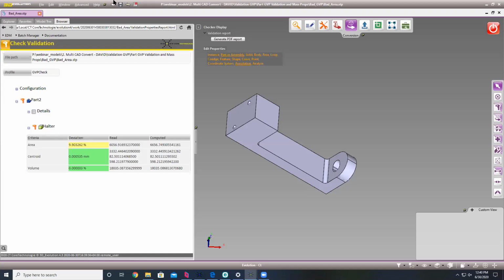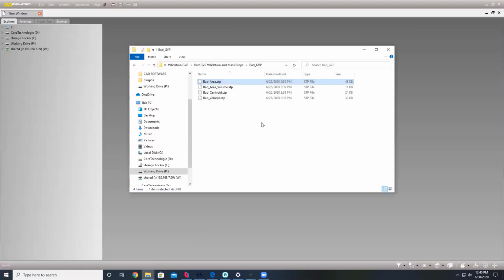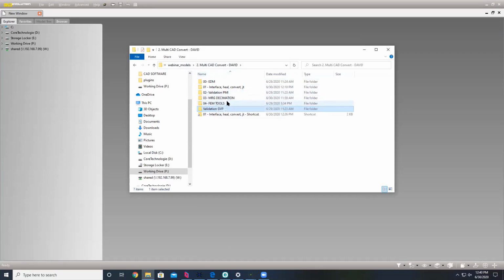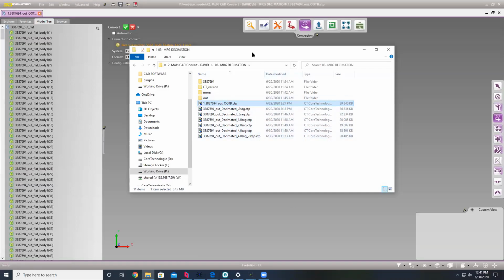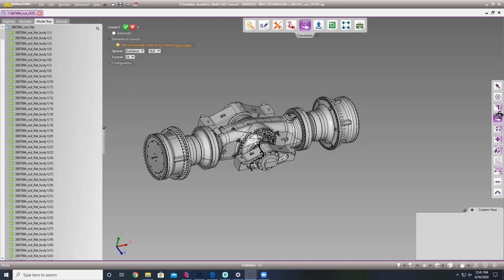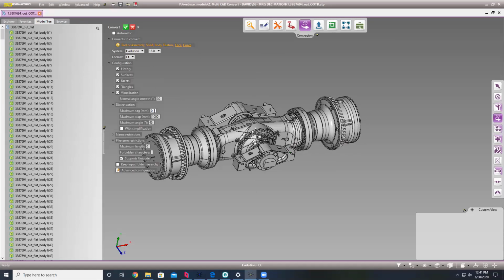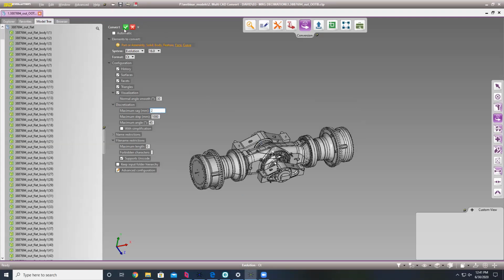And at this time, I have run out of time. But Michael, I know I'm out of time. Can you just take this file and save it with decimation, or show them the results of it? One of the things that happens in the industry is sometimes you're just visualizing a file, and we use MGR decimation to reduce the file size, because some of these files get really large. He's just going to hit file and save, but he's going to decimate it. And when I talk about configuration of decimation, he's going to change the minimum sag to 2 and convert it.